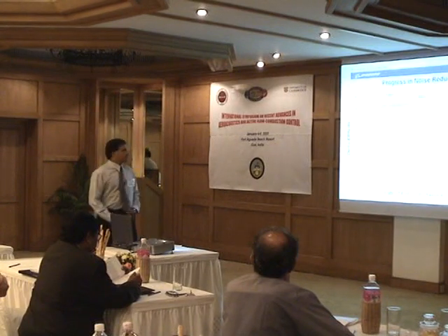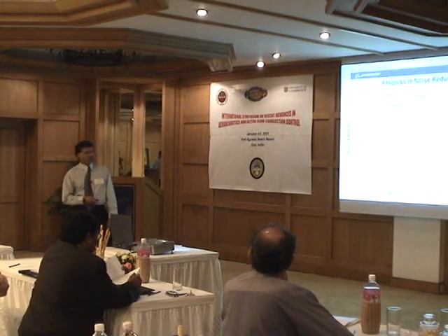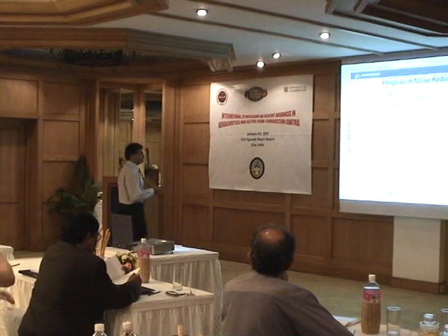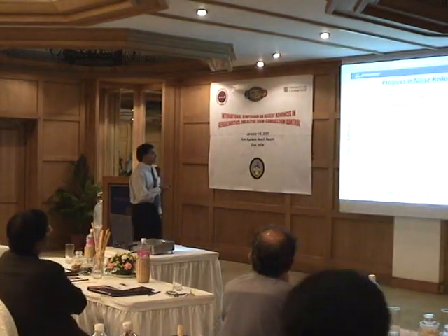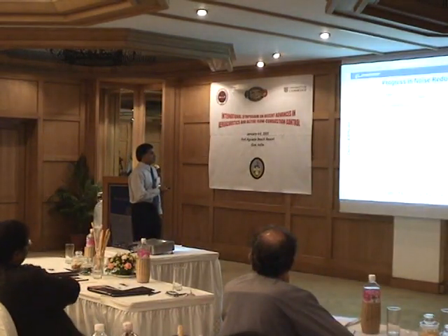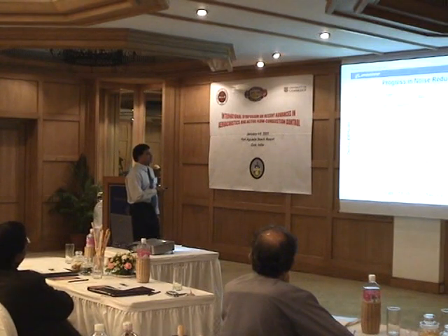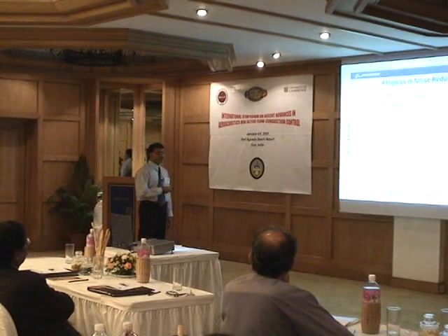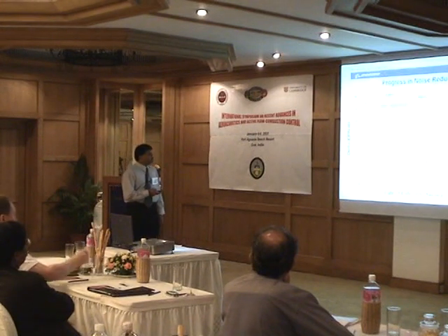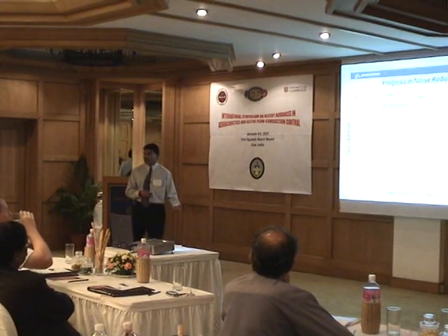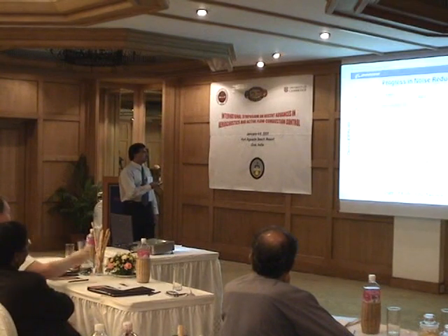Now let's look at the progress in noise reduction in the history of aviation, right from the early 50s. These are all the planes that have ever been built and flown. It starts with the 707, etc. And the red ones are the early planes powered by the turbojets and low bypass ratio turbofans. Then you came to the first generation of the high bypass ratio turbofans in the early 70s, especially for the 747. And the bypass ratio jumped from somewhere around 0.3 to about 5, and you saw a dramatic drop in